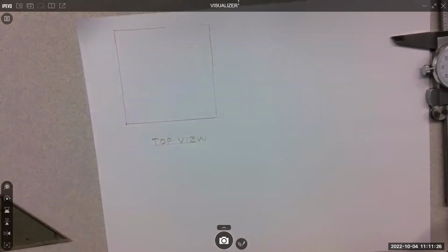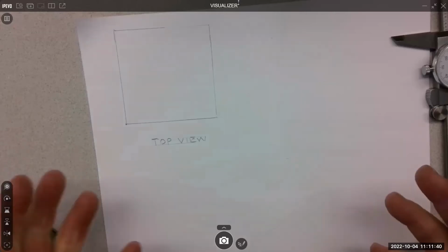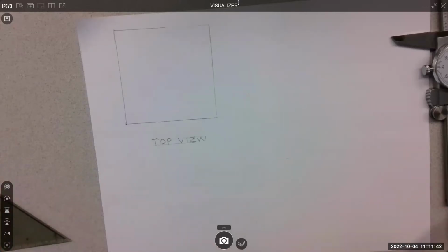Right? And I'm going to go top view. Name of the view, always under the view. So don't be sticking it off to the side because you didn't plan. Right? It's got to go under. I will hit you for that, because when we end up with 6 views on here, we need to be able to find the name of the view quick.